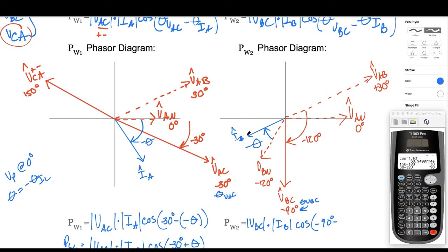Question. What is my overall angle of theta IB? So not just the difference from our B phase voltage to our B line voltage, right? We know the difference between here and here is minus theta, but now we want to know all the way from 0. Look at this. If I start from here, let's use pink, make it really stand out. Let's go all the way from here to here. How much is this from here to here? Minus 120. And then we want to go slightly more, which is going to be what? Minus theta. So here's a parenthesis, right? Minus 120 minus theta.